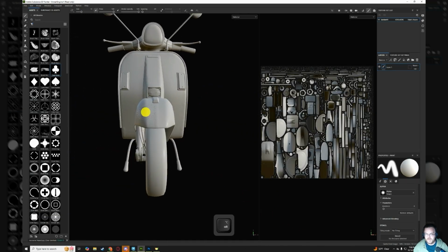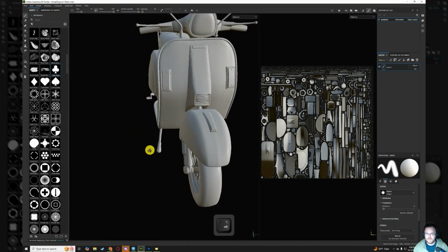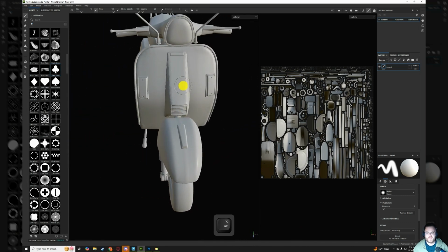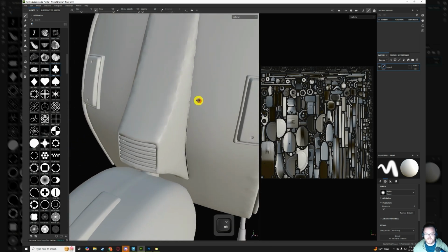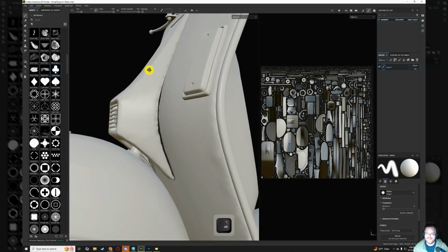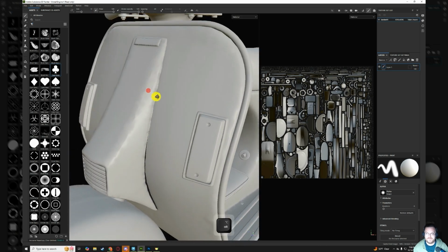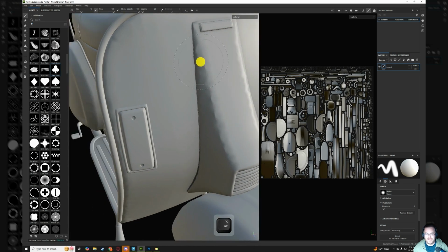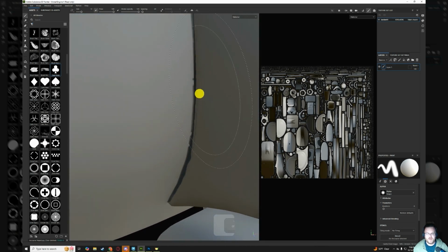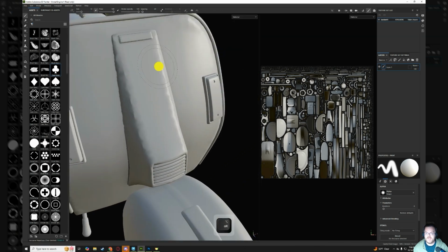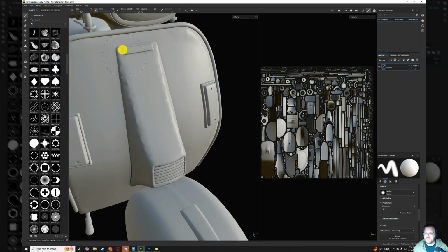And here is our baked mesh. I probably should have double checked to make sure that my reduction was actually okay, because you can see this kind of issue here on the edges where the normal map didn't really collect the detail properly.